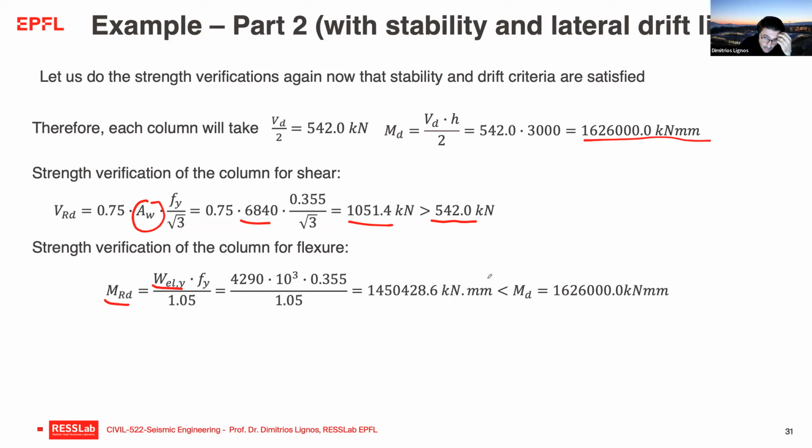So now the question is, do you want to redesign the system so that it will remain purely elastic, or could you consider something that you've learned in structural steel design, where you've heard that we are allowed to do plastic design because this is a class 1 or class 2 member, and plastic design is allowed.